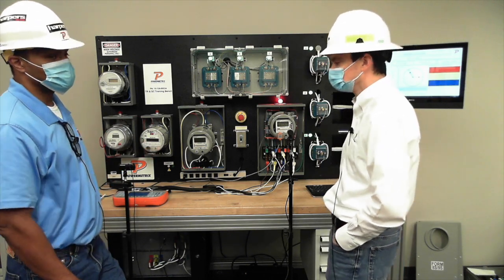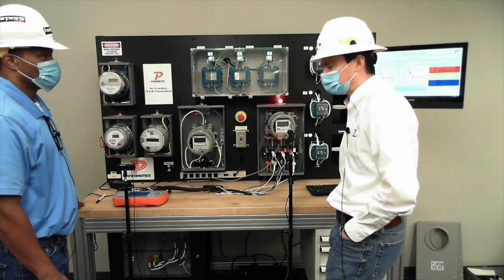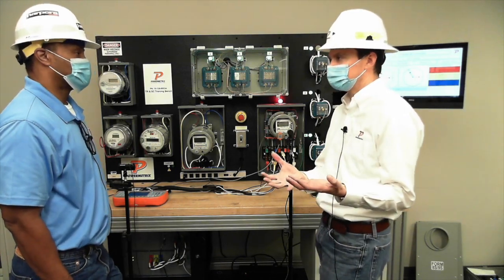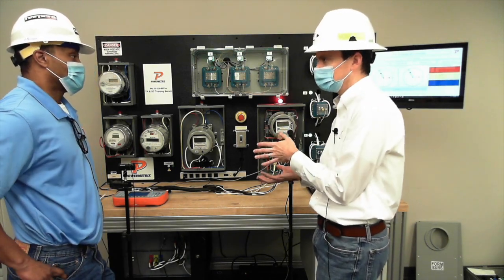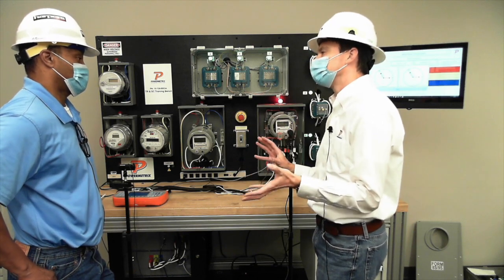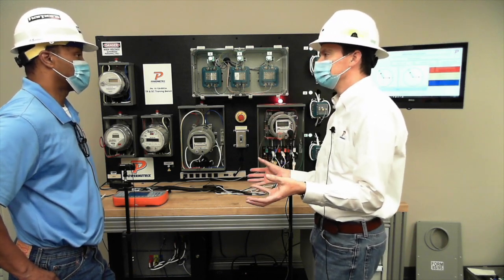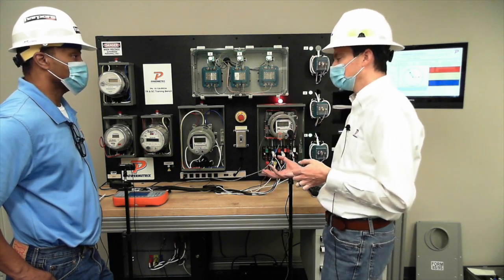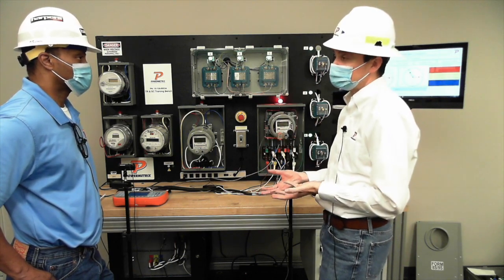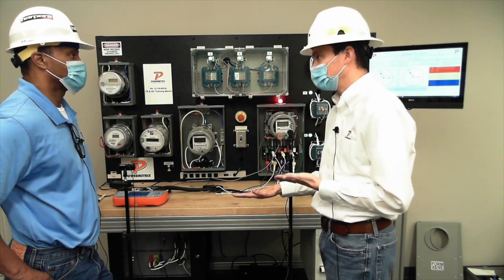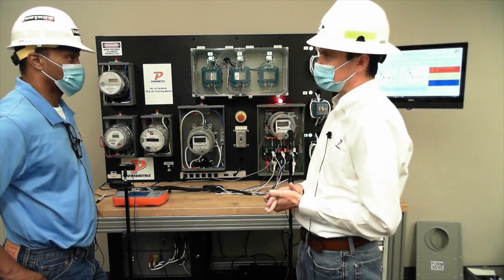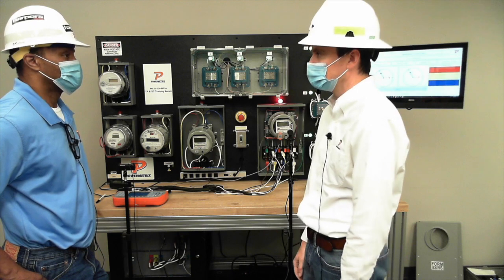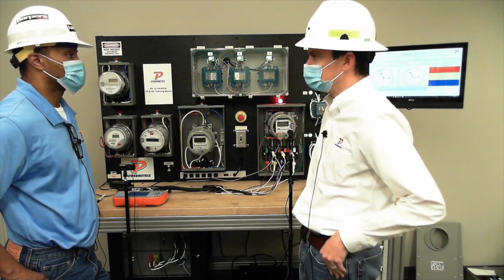Now, I believe, and correct me if I'm wrong, if you do a demand test, you don't have to do a register test, and vice versa. It's telling you pretty much the same thing, because it's looking at consumption of either power, energy, demand, power, register test, energy. A meter test may be able to give you the same answer in a shorter period of time. At least you can verify the meter registration is accurate. And then you do the demand test, 15, 30 minutes, whatever your interval is based on.